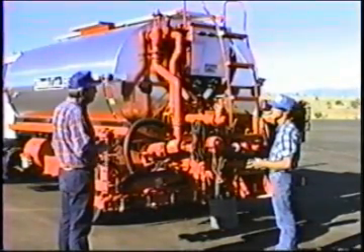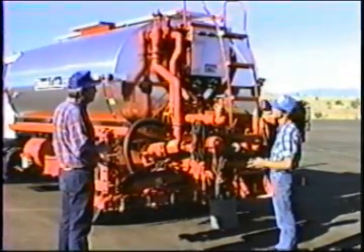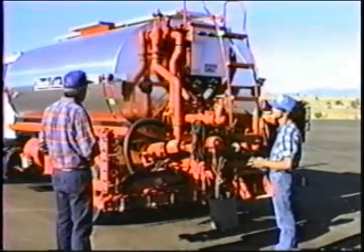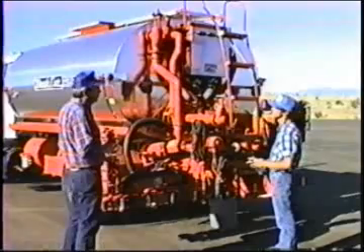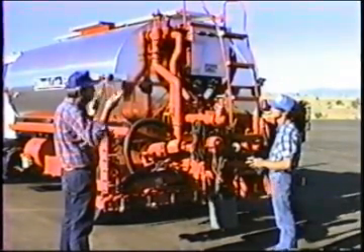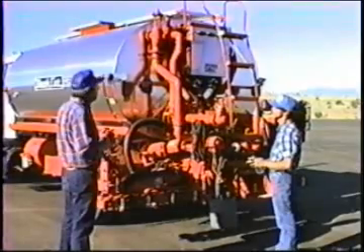So if we boil a gallon of water in the bottom of that tank, it instantly turns into 3,000 gallons of steam, and that has to displace something. Everything has to be someplace, and if you instantly make 3,000 gallons of steam in the bottom of that tank, it's going to crowd some asphalt out of the tank in order to make a space for itself. And it does that very violently.